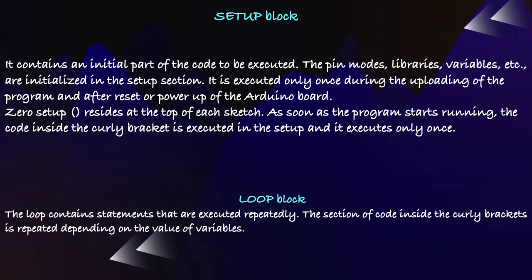Void setup resides at the top of each sketch. Dear students, a sketch means a file that we are running; in Arduino language, it's called a sketch. As soon as the program starts running, the code inside the curly brackets in the setup is executed only once. That is the basic purpose of a setup block.